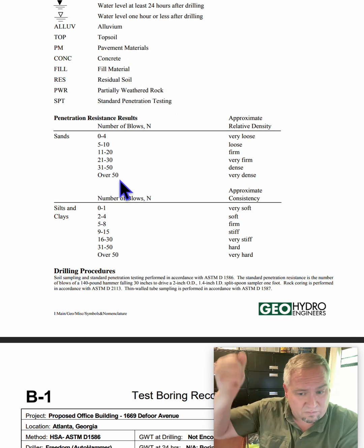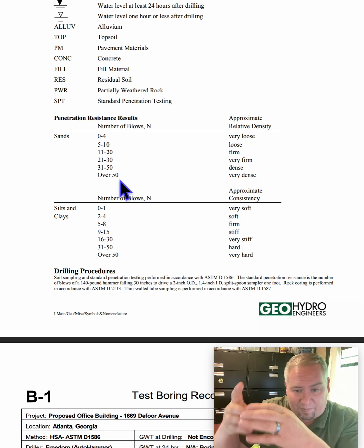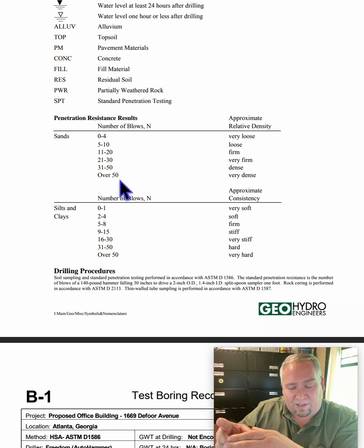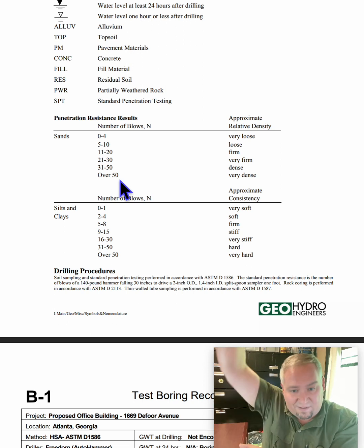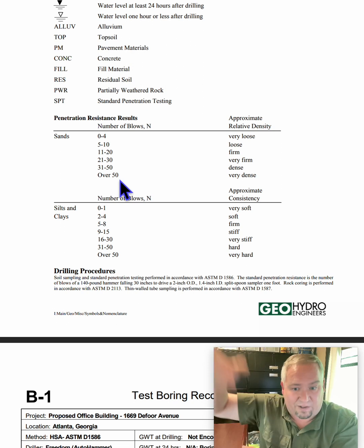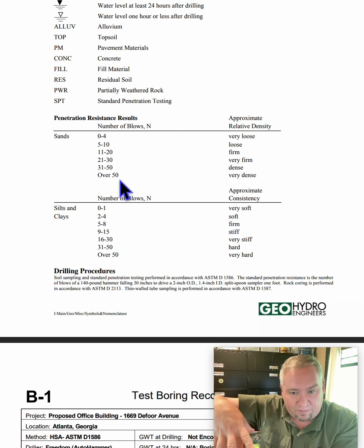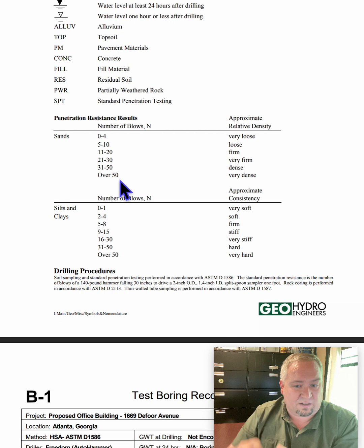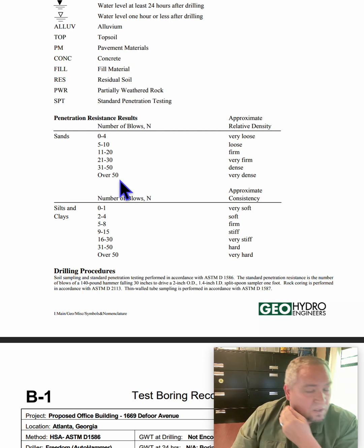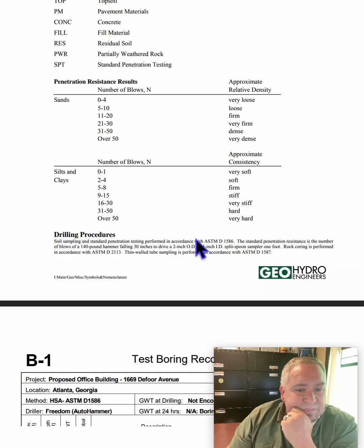And this machine has got a pipe that's going down through there, taking a core sample, and it's got a big weight up above it. And it slams down on it consistently. They have a rope that pulls it up, and then it drops. Pulls it up, and drops it. And the geotech sits there and just counts. 1, 2, 3, 4. So until it meets a foot, then he marks it down on this report.